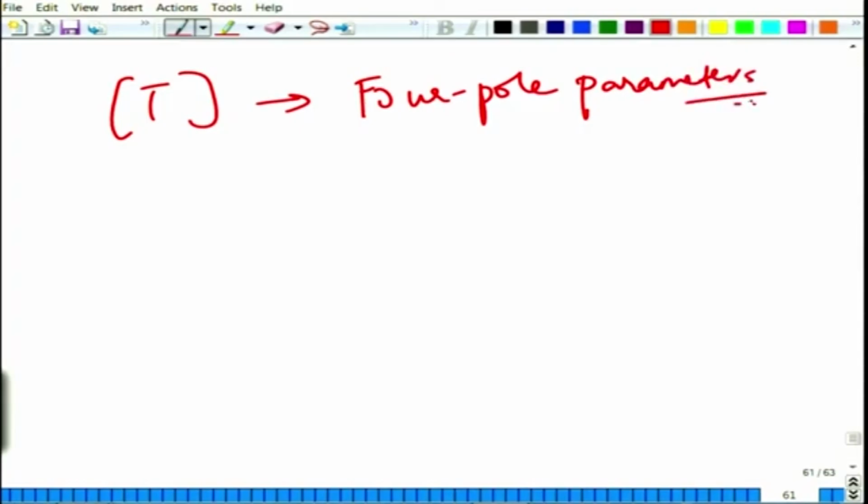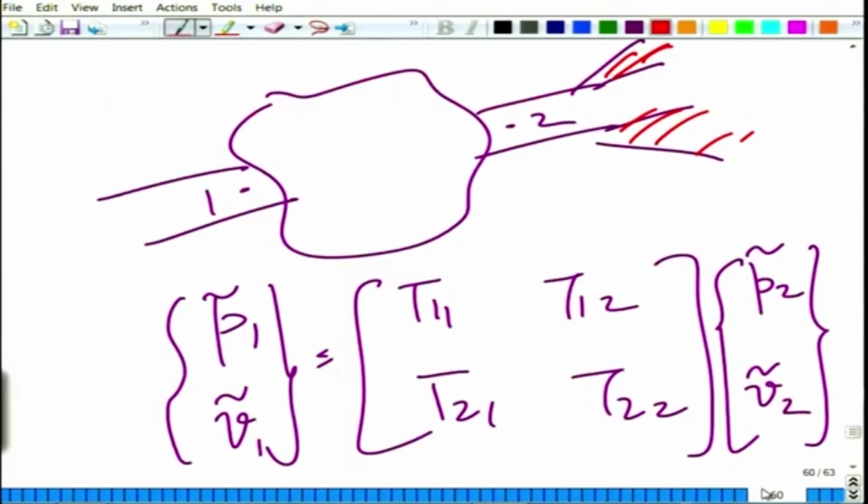Okay. So, what we intend to do now is derive a generalized expression for the transmission loss for a general element in terms of the 4-pole or T matrix parameters T11, T12, T21, T22 for a stationary medium, once we know the inlet and outlet diameters. Based on this generalized expression, we are going to get a feel for where you can expect resonance peaks, where the transmission loss will exhibit an attenuation peak in the spectrum, or where it can exhibit a trough.